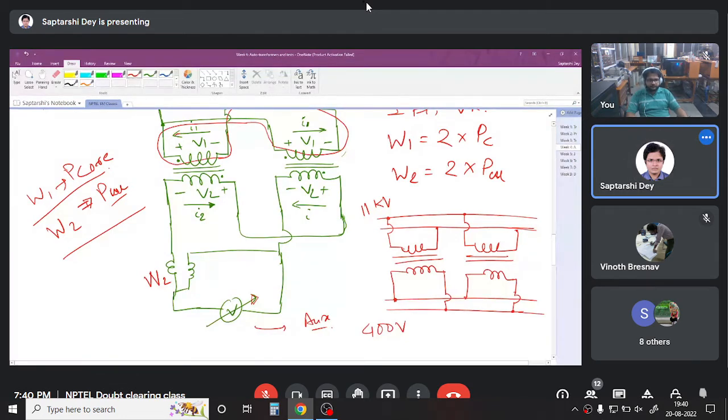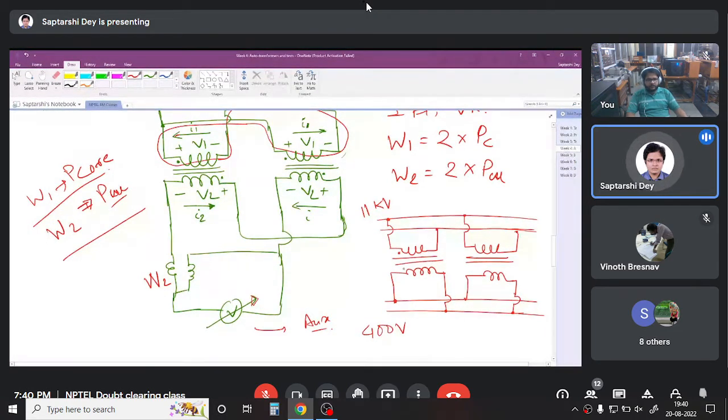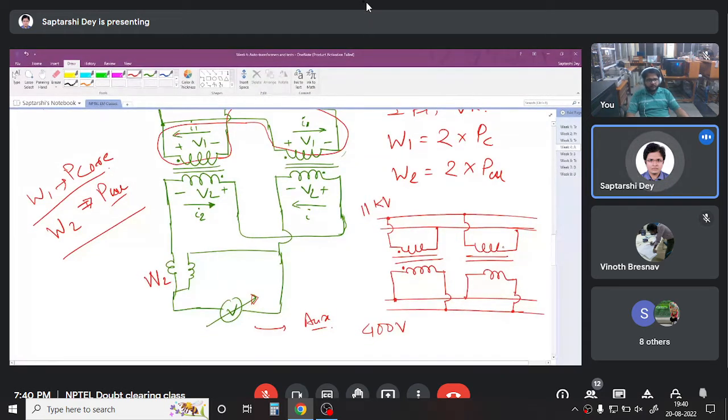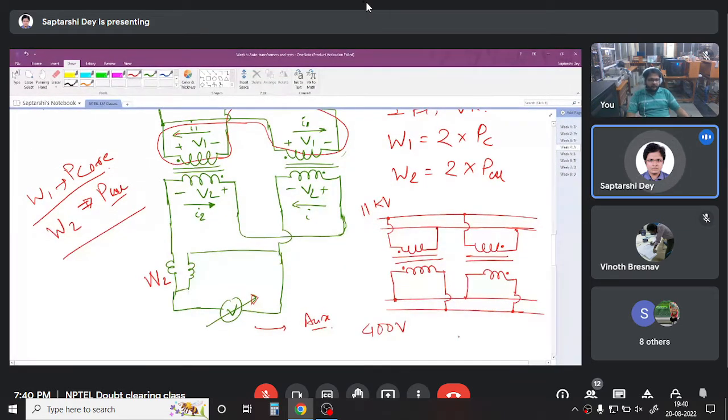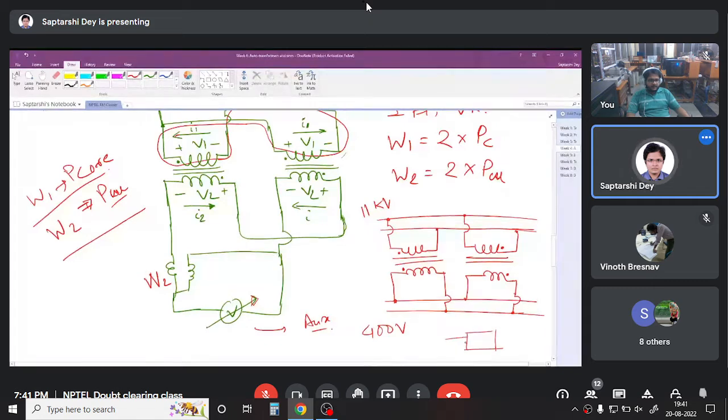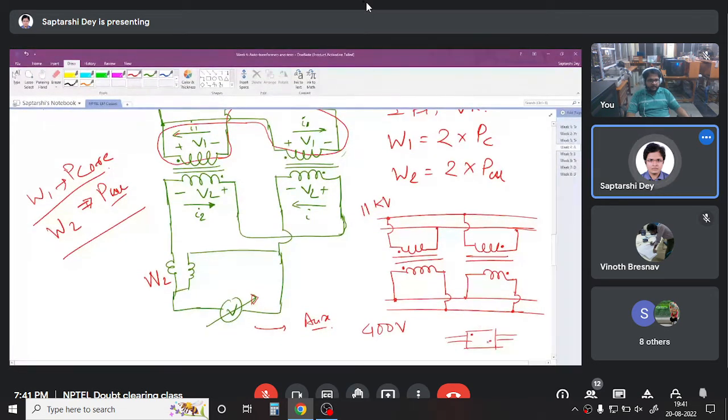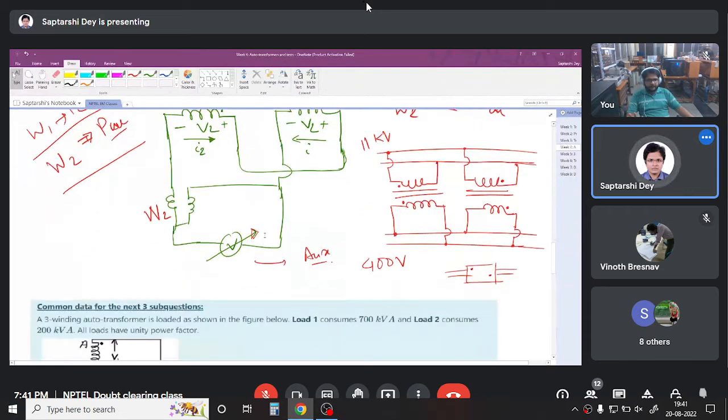So in these cases, you cannot connect them in any way. So if you have a dot here, and suppose the new transformer that you have installed is on the lower line, you have to give a dot here also. I'm not saying that you have to give the dot. The new transformer comes with the dot convention painted on it. Looking at the dot convention, you have to connect the transformer such that the arrangement is like this. Is it clear? You are not giving dots. The transformers come with the dots painted on it.